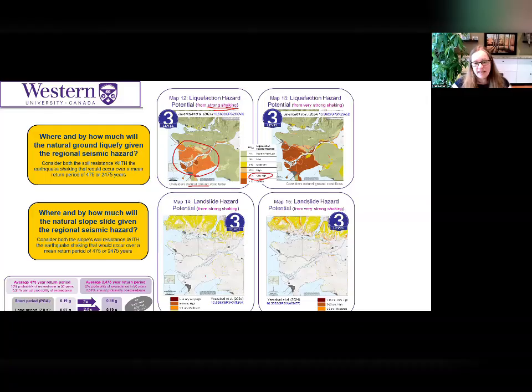An opposite case almost is that the landslide hazard potential map is all yellow or all low at the strong shaking level. We kind of need very strong shaking to trigger a lot of landslide failures. In our calculations for the slope angle, the older glaciated or Pleistocene age and cohesive clay-like materials define a lot of the slopes.